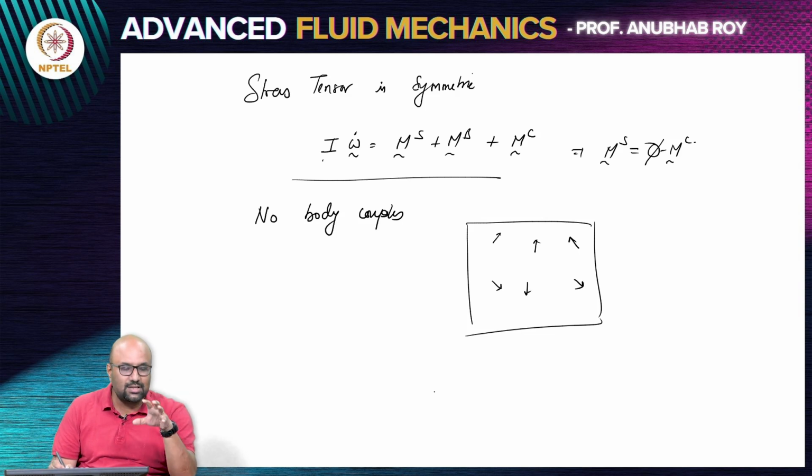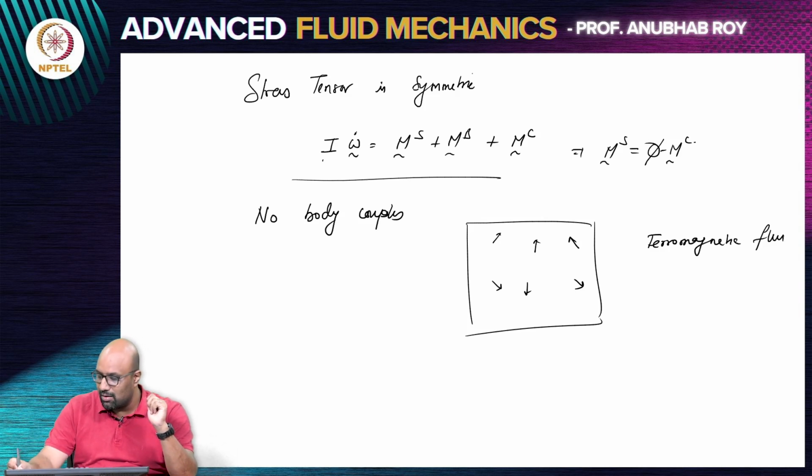So each of these tiny magnetic particles which are suspended in the fluid has its own moment. So you have a local couple in the problem. In which case, when you are trying to derive this relation for the stress, you need to account for the fact that the fluid locally can have a couple present. This can happen when you are treating problems which have the ability for local body couples. A ferromagnetic fluid, or ferrofluid, is one example.